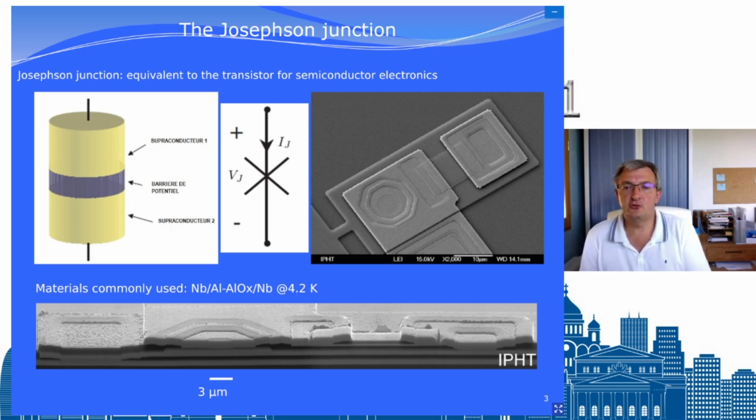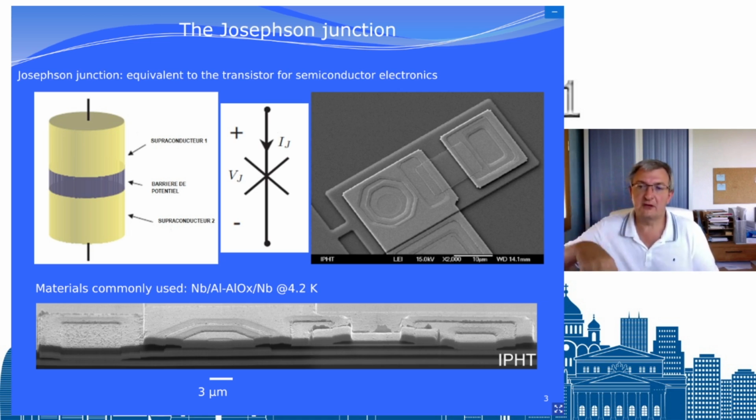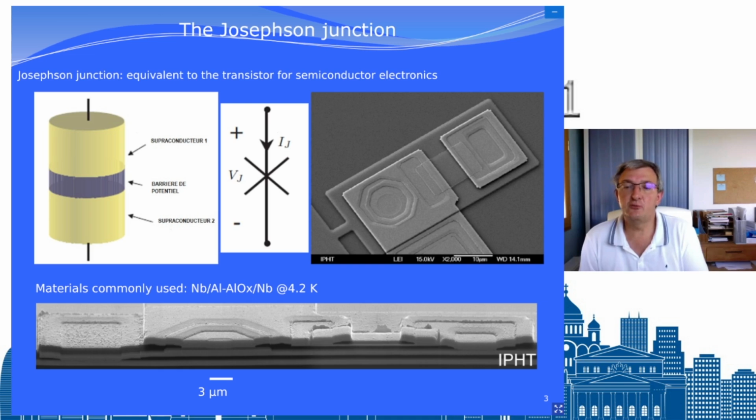And after you take a wire of another superconductor material, you make it sharp, like an arrow, and then you press it against the other material, which is insulated. If you press enough, at some point you will have the right thickness of barrier made by the insulator, which covers the first superconductor, and you have a Josephson junction.